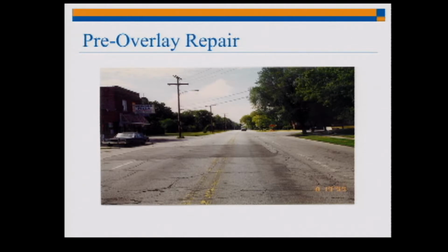This is just another example that although this looks like it's in pretty bad shape, there have been plenty of bonded overlays placed on pavements like this. So you may have sections that are not in great shape and you may have to do a patch or something, but when you apply overlays of the nature I'm talking about, you're not expecting these to last 30 years. You're thinking 15 to 20 years as your design life, okay?